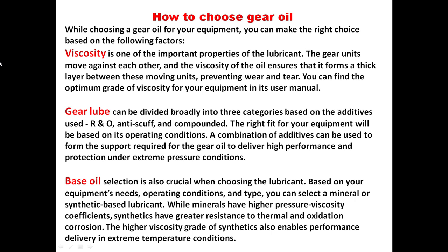The third one is the base oil. Selection is also crucial when choosing a lubricant. Based on your equipment needs, operating conditions, and time, you can select a mineral or synthetic based lubricant. While minerals have higher pressure viscosity coefficients, synthetics have a greater resistance to thermal and oxidation degradation. A higher viscosity grade of synthetic also enables performance in extreme temperature conditions.